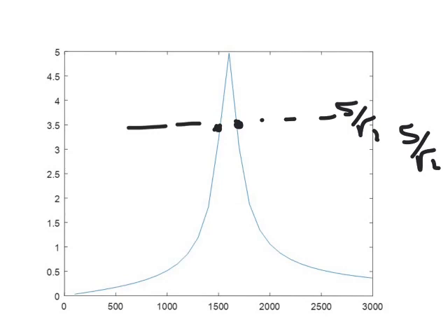This is a band that's allowed to be transmitted by this filter, and everything else is being blocked. As you see, it tries to kill all the other frequencies. It does not allow them to go through. So if your source has multiple frequencies, in our case here it has only one frequency. If it has multiple frequencies, the resonance frequency will go through without any change. Actually, you get a reduction of 1/2, because this circuit becomes like a voltage divider. At all other frequencies, you see a strong reduction in the amplitude of the output voltage.